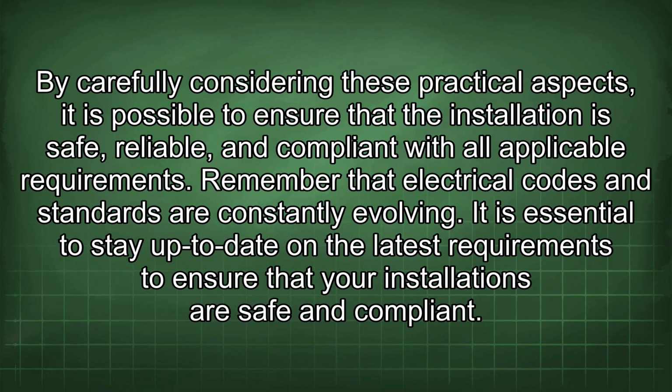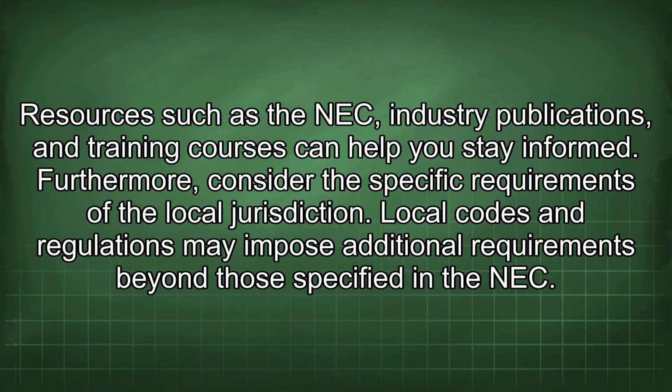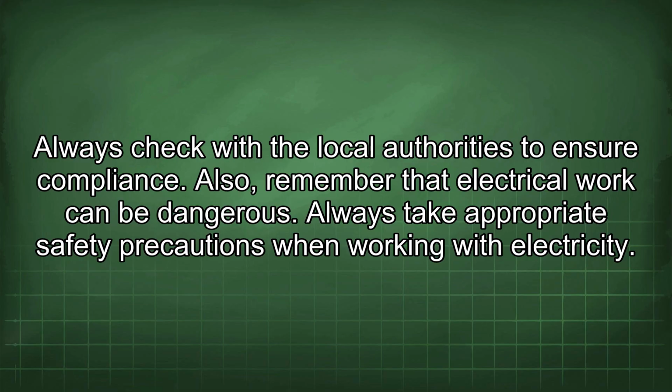It is essential to stay up to date on the latest requirements to ensure that your installations are safe and compliant. Resources such as the NEC, industry publications, and training courses can help you stay informed. Furthermore, consider the specific requirements of the local jurisdiction. Local codes and regulations may impose additional requirements beyond those specified in the NEC. Always check with the local authorities to ensure compliance.